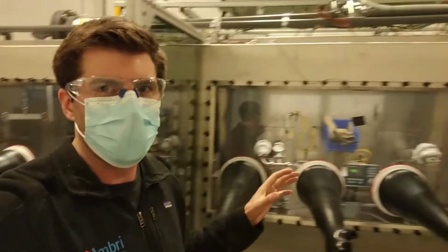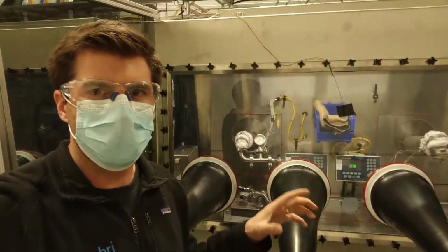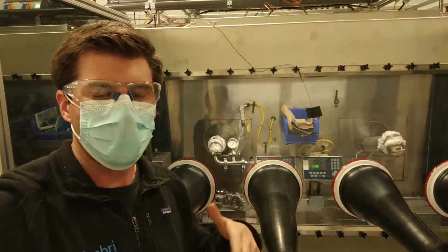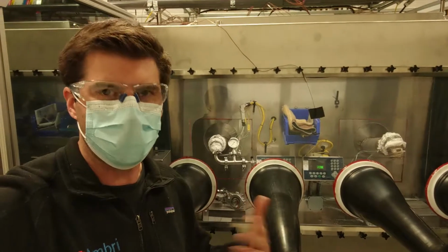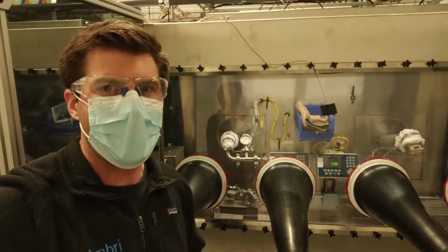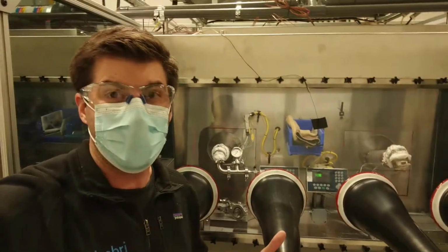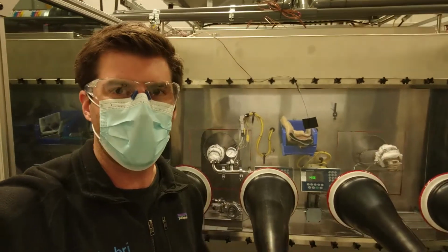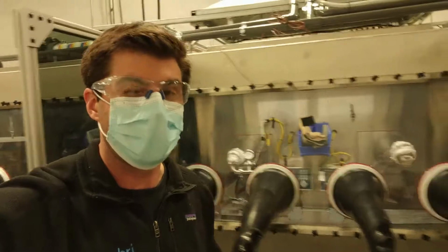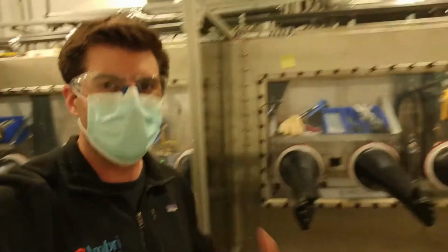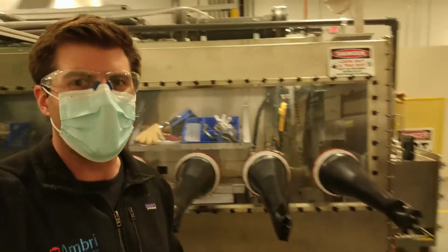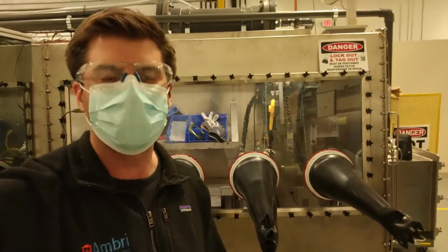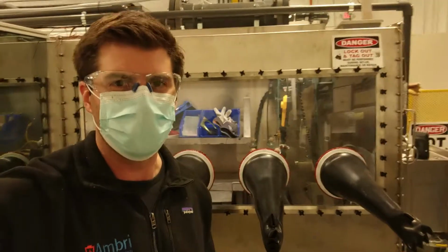Cells are then slid over and filled with molten salt that is poured through these 2 pouring tubes here, and we control the flow of the molten salt using a mass-based control system, and that's it. Once that's done, the cap is sealed up with an extra weld on the top, and the cells are ready to be tested. It's really a very simple and elegant process that allows us to project to be a very low-cost manufactured cell product compared to many other cell technologies.